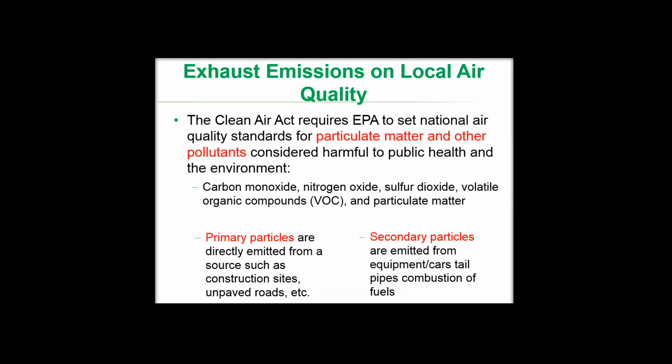If we look into the exhaust, which is the first 2 points I mentioned, the exhaust emissions on local air, the Clean Air Act requires EPA to set the national air quality standards for particulate matter and other pollutants that are considered harmful to human beings, to public health, and to the environment. This includes the non-methane hydrocarbons, carbon monoxide, nitrogen oxide, sulfur oxide, volatile organic compounds, and particulate matter, as well as carbon dioxide. These are coming from primary particles as well as secondary particles.